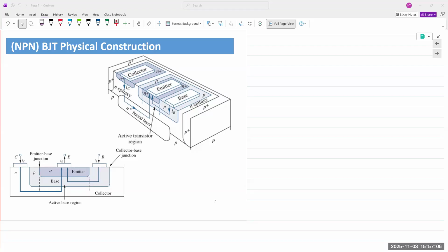If it's a P-type base structure, electrons are minority carriers. And if they're minority carriers and you reverse bias the second P-N junction, what happens to the minority carriers in P-type? They're able to cross over the junction because they're attracted by the positive. They are now reverse biased. And so now they're attracted by the positive voltage applied to the collector junction, and a heavy amount of current starts flowing out of the collector.